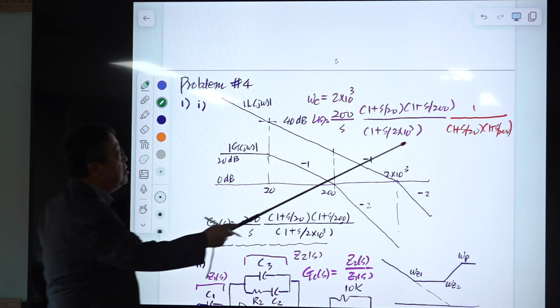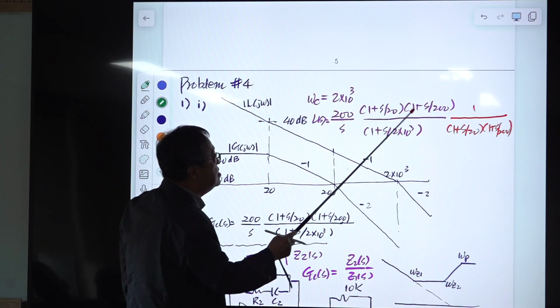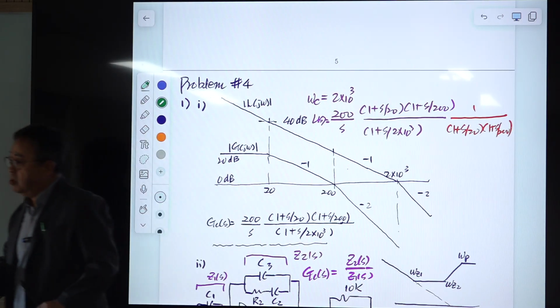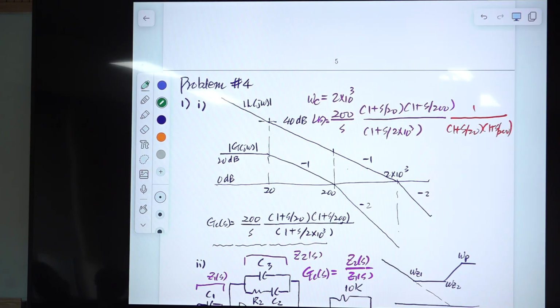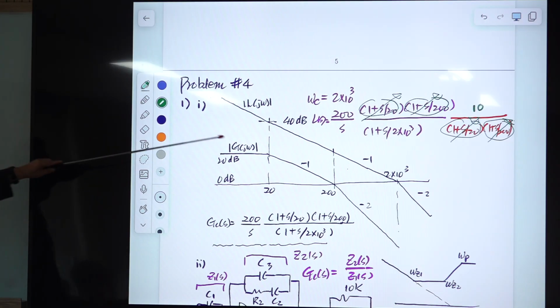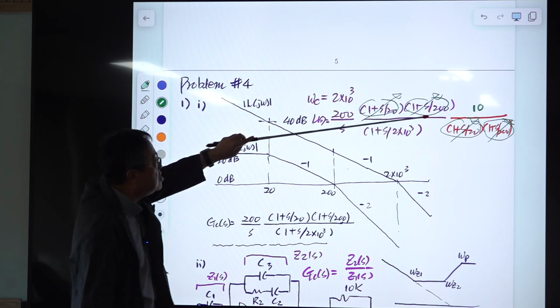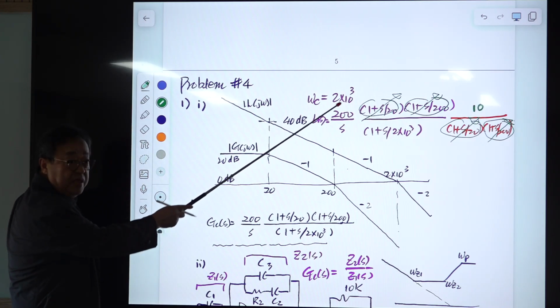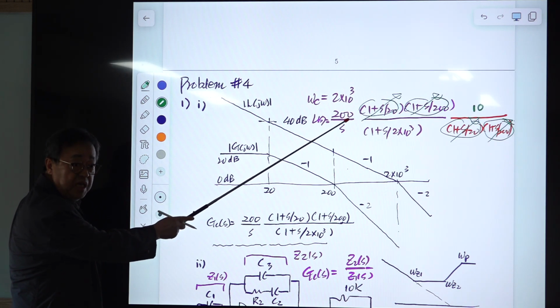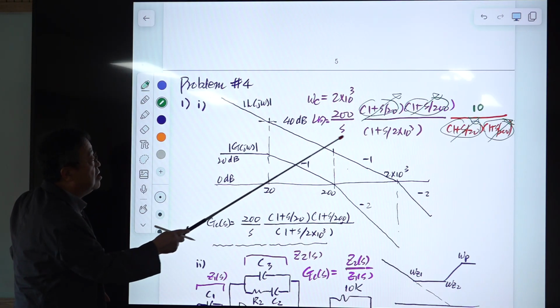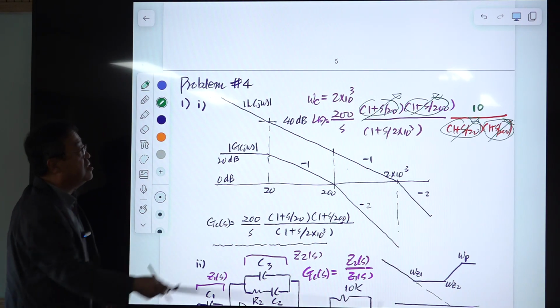So this is the plan. It has 2 poles, then cancel these poles with 2 zeros. So place 2 zeros here. This zero and these poles, they'll cancel. All right? And here, this is 10, right? Then select the integrator gain as 200. Then the total integrator gain is this times this. So we'll have the crossover frequency at this desired omega c. So just select these 3 numbers and the structure.